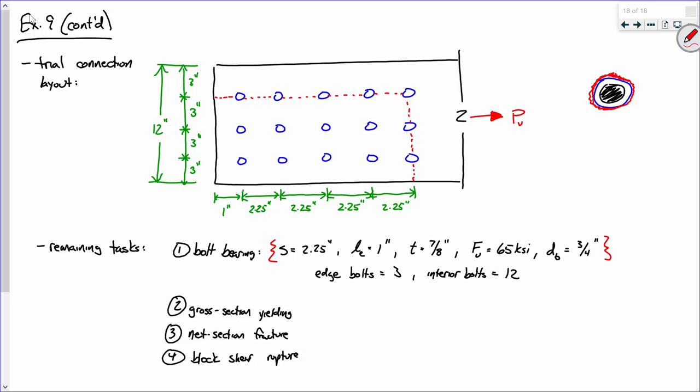That's probably the most common one, because just looking at the dimensions, if I had another shear path going like this, again, your block shear paths have to surround all of the bolts in the connection. When I'm defining block shear paths, I'm trying to define the path with the smallest amount of area, because that's more than likely how it's going to rip. Does that sound good? So you could have a path that goes down, over, and down, but that's another 10 inches of area in shear, and you're losing only 3 inches in tension. It's more likely it's going to fail the other way than with all that additional shear path. Does that make sense? Everybody okay with that?